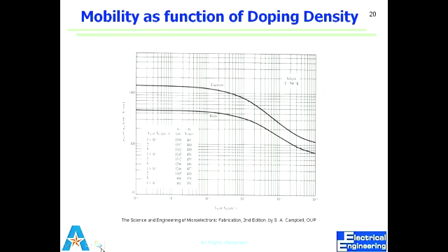It's your resistor, but resistors are different in N-type and P-type, because their mobilities are different. Holes are fat. Simple way to remember, holes are fat. There was something contained in that hole, which was an electron. So the electron is smaller, the hole is bigger. So holes have more mass, and fat is lazy to move. So hole mobility at the same concentration is always less, and it falls down in the same way as electrons.